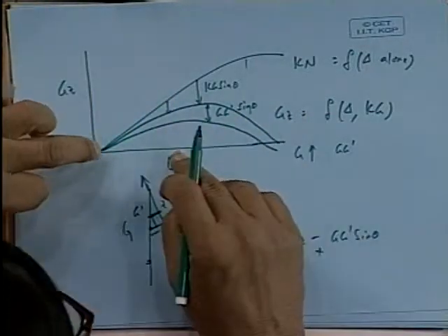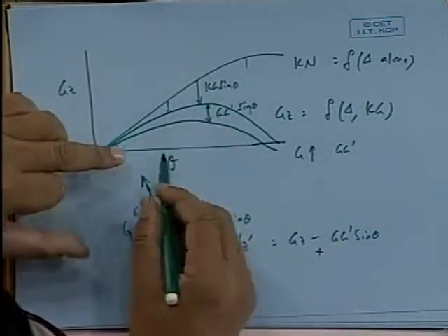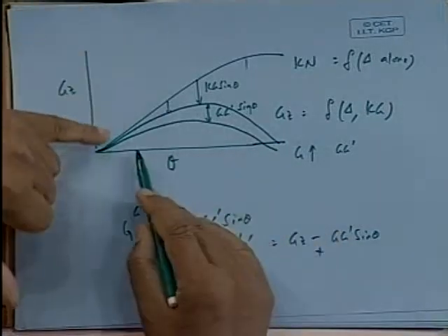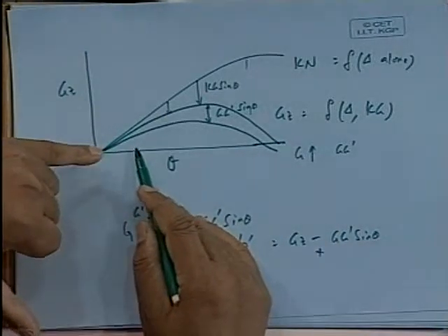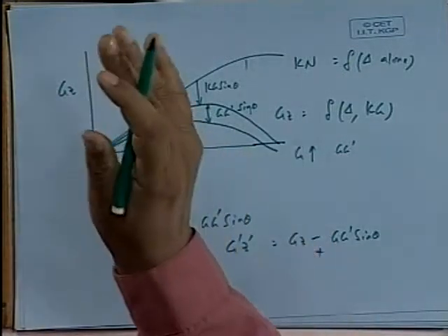For static stability curve, although it is simple, it is something like this. Establishing this curve from cross curves is trivial, one line, but the property of the ship's stability characteristics are contained in this curve, not in KN curve. KN curve is simply like a database. That database is there for a hull, so you have calculated once for all. Now from that you will actually find out for your condition what is my static stability. But that transformation from cross curves to static stability, that I will write down here.